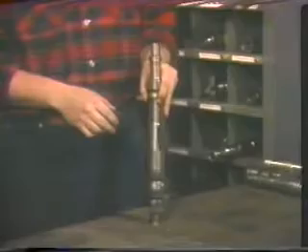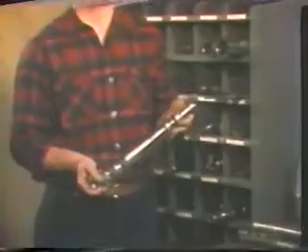The slip lock can be used to anchor plugs, safety valves, pressure regulators, or bottom hole chokes. These locks are usually limited to use in low volume, low pressure wells. This is because slip locks have a relatively small flow area through the bore of the lock and limited pressure ratings because the lock uses the tubing wall itself to anchor the lock, and the condition of the tubing will deteriorate with time. Most wells today are completed with future wireline work in mind and have a series of receptacles